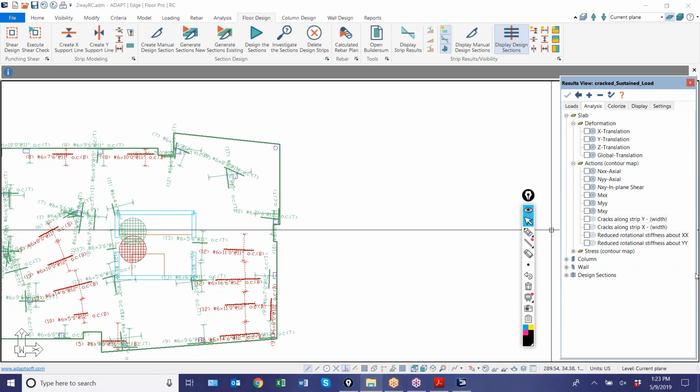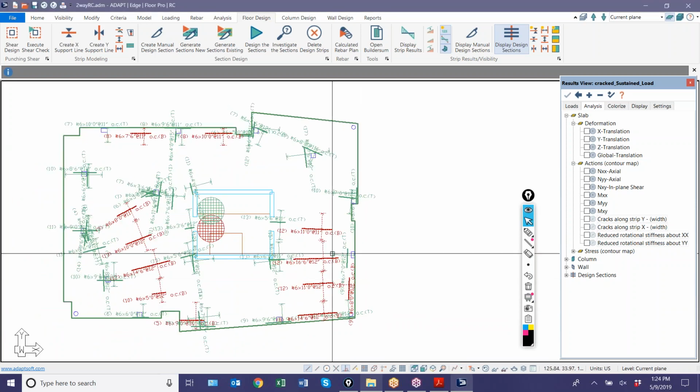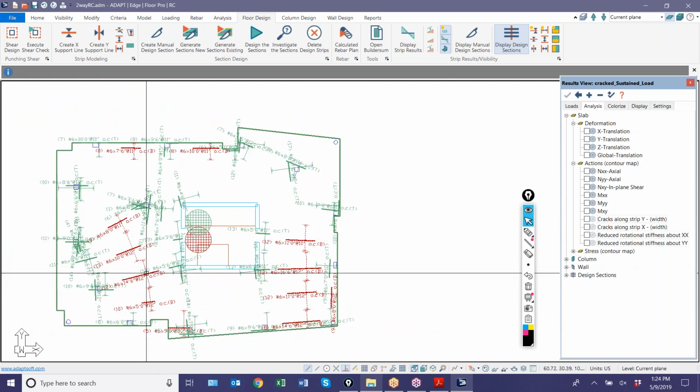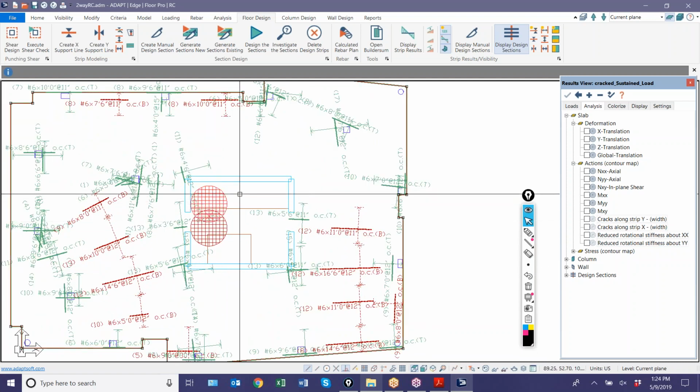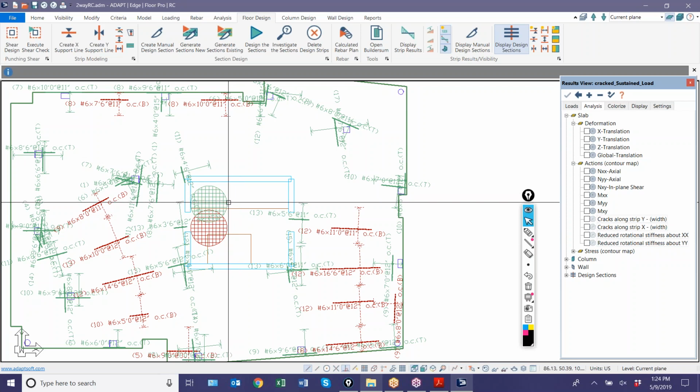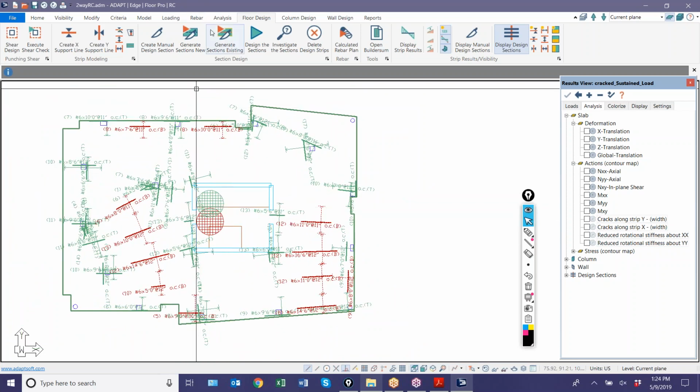The question is, even though we specified the opening and added splitters around the opening, rebar has been designed in that area, and can we avoid mesh reinforcement at the opening? Yeah, you can avoid mesh reinforcement in the opening if you don't use the wizard.